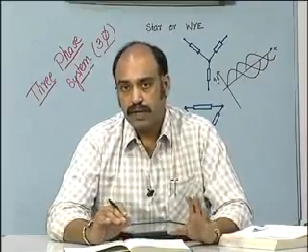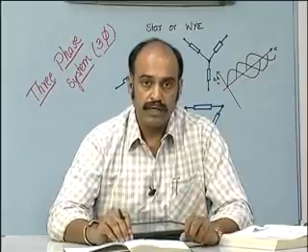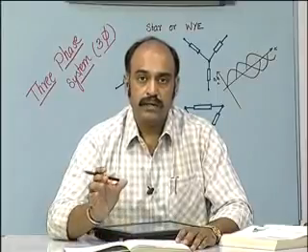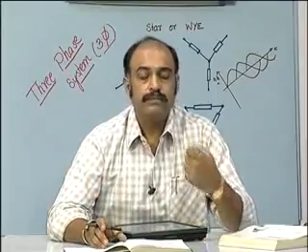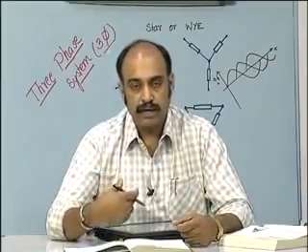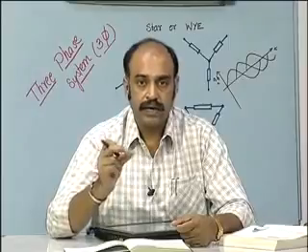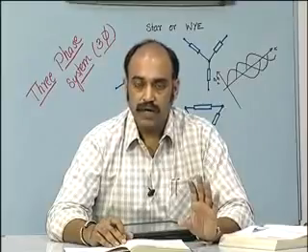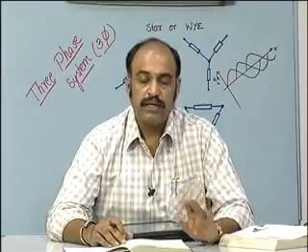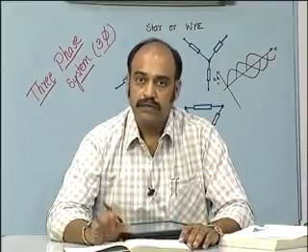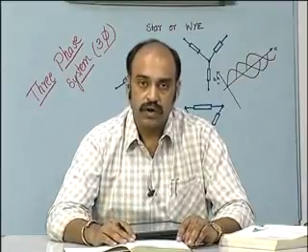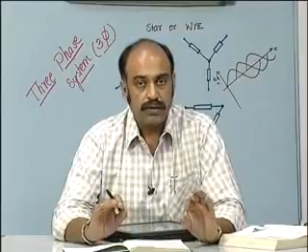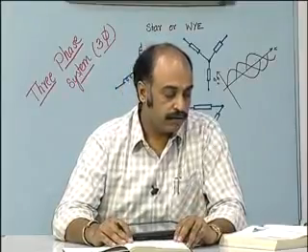The other method is by using watt meters. One may use 2 watt meters in the case of a 3-phase 3-wire system, that is, where the neutral is not available. One watt meter may be connected to one of the lines, and the other watt meter connected to another line, with the potential coils having the third line as the reference. Then the readings of the 2 watt meters are summed up to get the total power drawn from the source.